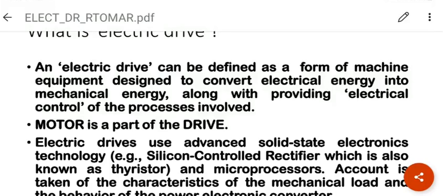Motor essentially needs either AC voltage or DC voltage, depending on its nature. And if it is AC voltage, it can be three-phase or single-phase. In case of DC motors, it is the voltage input that has to be controlled properly and in a continuous manner to get the best out of the motor. In case of AC motors, it can be voltage as well as the frequency of the signal coming in that can be controlled. Methods, of course, are several.